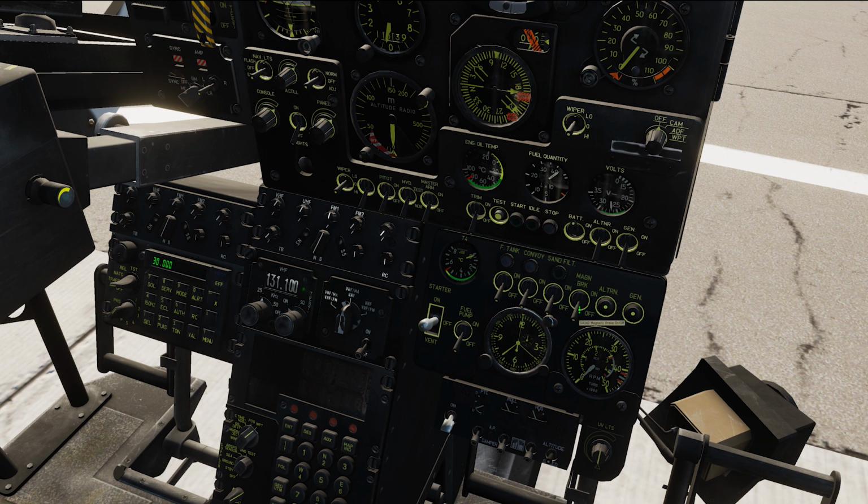So the next switch we talk about is the magnetic brake, which will also be turned on with the startup, which we do later on. The magnetic brake is used to trim our cyclic. So we have a trim button, and we can put the cyclic in a position and hit the trim button and use the magnetic brake for trimming. The alternate and gen rearm are not implemented, and I don't know what they are doing.